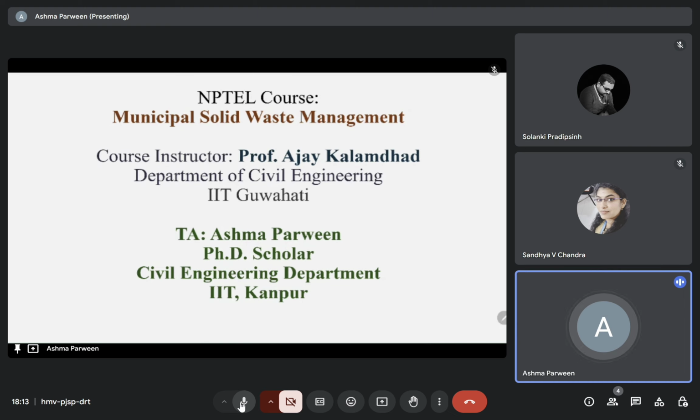So this is basically a combination of thermal and chemical conversion. After that, we moved to biological processing. In biological processing, we discussed composting, and then vermicomposting. Basically in composting, there is a degradation of the waste, or a conversion of the waste into lesser complex organic matter by microorganisms. These microorganisms or microbes feed on the organic waste. Basically, they are aerobic microorganisms.